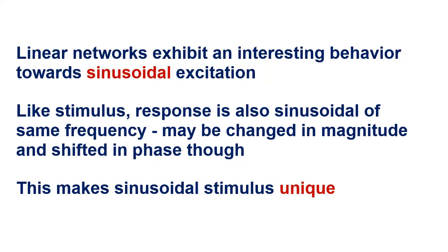We will discuss sinusoidal excitation now. Linear networks exhibit an interesting behavior towards sinusoidal excitation. The response signal, like the stimulus, is always sinusoidal of the same frequency, but may be changed in magnitude and shifted in phase. This behavior is unique for sinusoidal excitation.